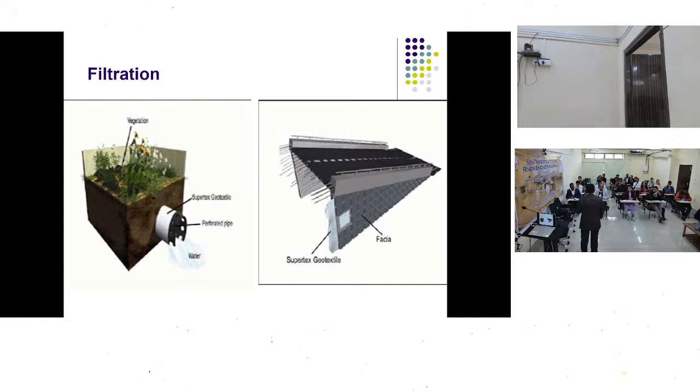The answer you will say is, okay, we can go for another non-woven geotextile which has an opening size less than the clay particle size. But then the permeability gets hampered, because the smaller the opening size, the lower the permeability. So to that I will have my non-woven geotextile and then I can have my perforated pipe. The sand particles will act like a graded filter, retaining the clay particles and allowing the water to pass through, and that water will pass again through the non-woven textile and out.